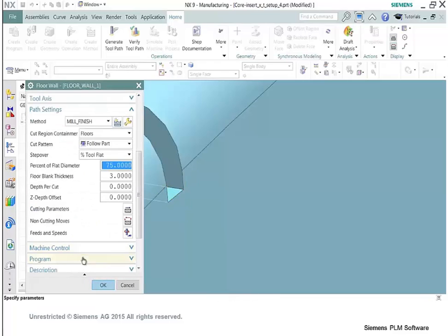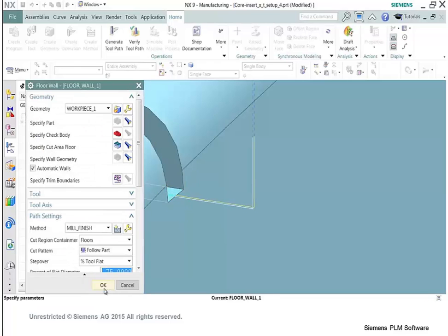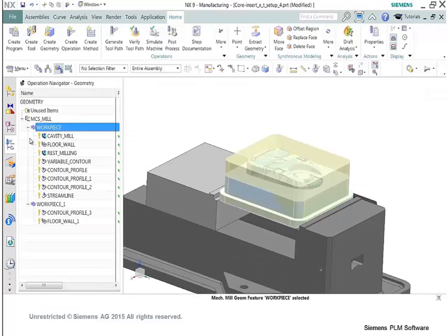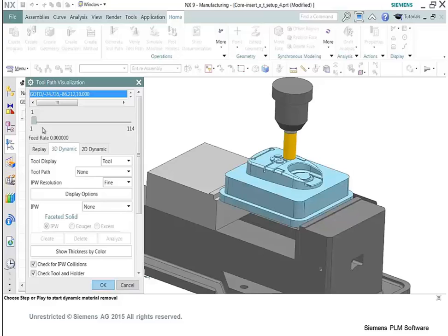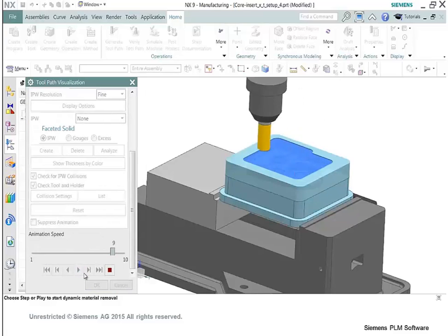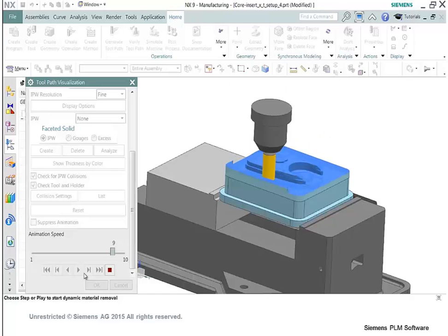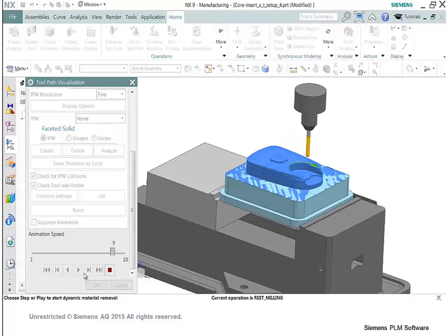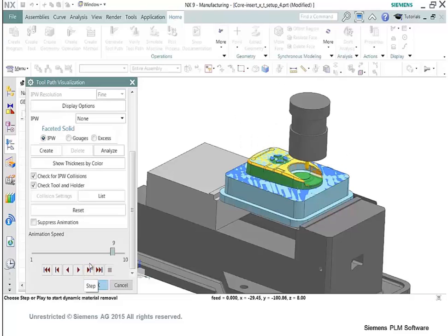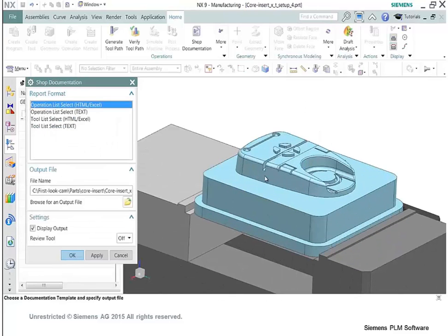So there you have it. We did the slots. We cut around the pockets. And we do the same thing. We complete a part with different workpieces, different stage models, of course. We can show you a change on that part. So if we change the original part, you'll see that the operation 1 part changes, and the stock will change with it and update it and transfer it to the next part, operation 2. No matter how many operations you have on the part, operation to the next operation.